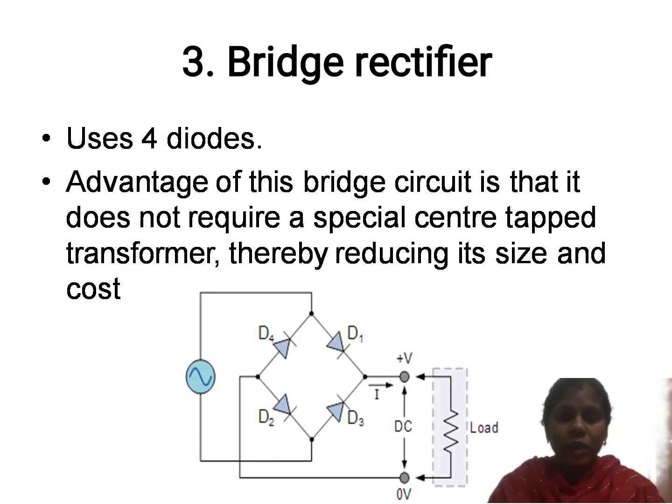This means only two diodes conduct for a positive cycle, that is D1 and D2, and the remaining D3 and D4 are in a non-conducting state, giving the output signal V0 equal to Vi. During the negative cycle, D1 and D2 act as reverse biased, as an open circuit, in a non-conducting state.